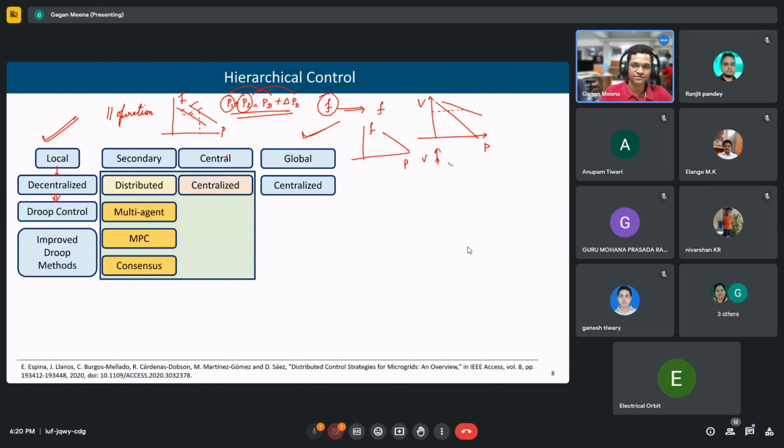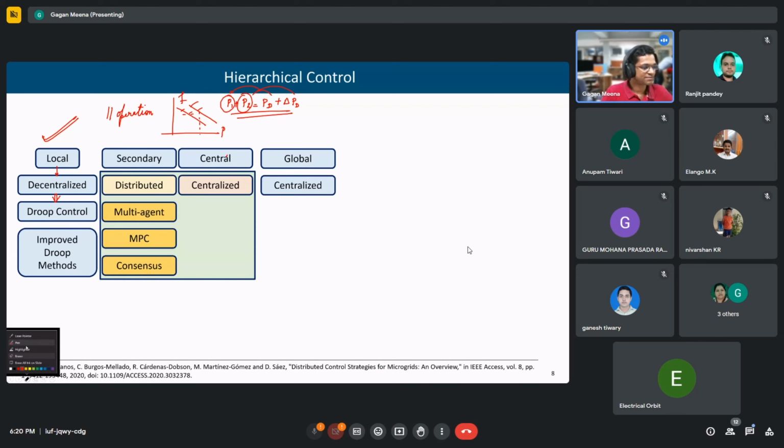These droop characteristics come into the picture when we are applying some load to the generator. So it tells us how the increase in load will be distributed among the parallel connected generators. So how the power or load will be shared, current sharing, power sharing, all this, is determined by this control. It is the local control, and it will determine how much that generator has to generate.